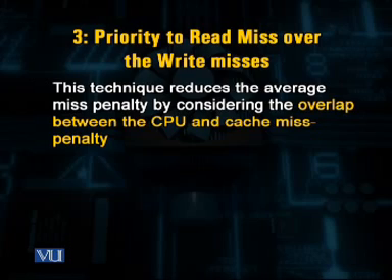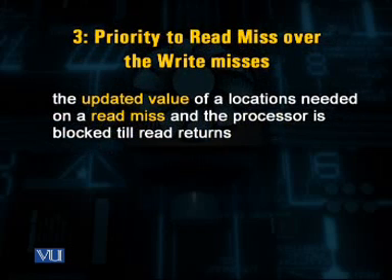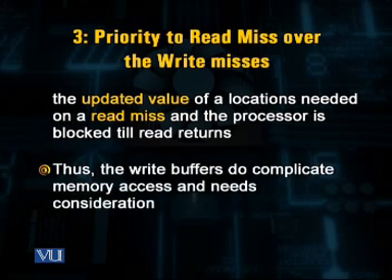Furthermore, the write buffer may hold the updated value of a location needed on a read miss, and the processor is blocked till the read returns. Thus, the write buffers do complicate the memory accesses and need consideration.